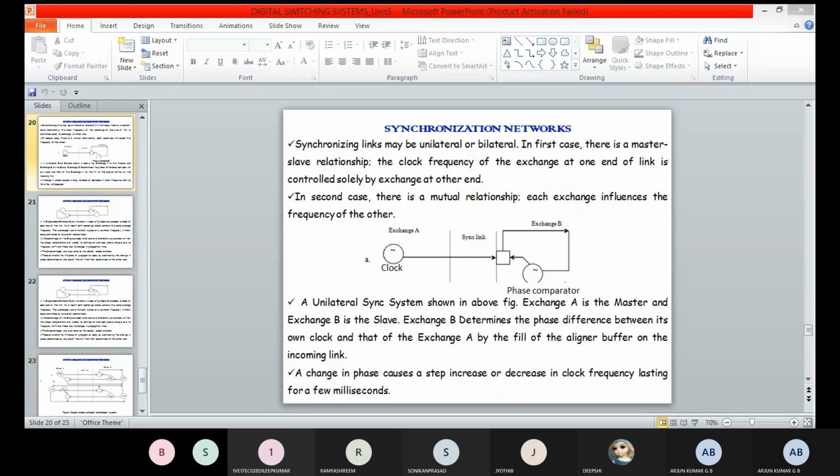Here in the bidirectional path, the switching network sometimes takes space time space switching or time space time switching. These switchings are unidirectional transmissions. Since the PCM transmission system uses 4-wire circuits, it is necessary to provide a separate path for sending and receiving the channel.